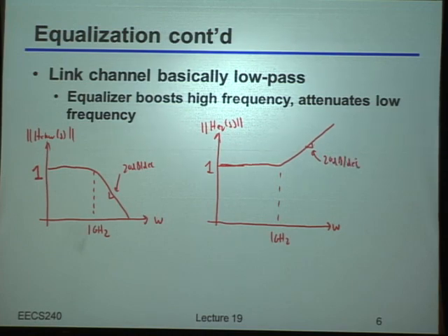All right, but now I want to ask you guys a couple of slightly more subtle questions. What we drew here was literally the inverse of the channel response. We literally just did 1 over H of S. So now I want to ask you guys, do I actually have to do exactly 1 over H of S or not? In other words, can I still get my equalization functionality without exactly doing the inverse? Okay, you said I can use a lower DC gain. By the way, is it just DC gain that I can play with?